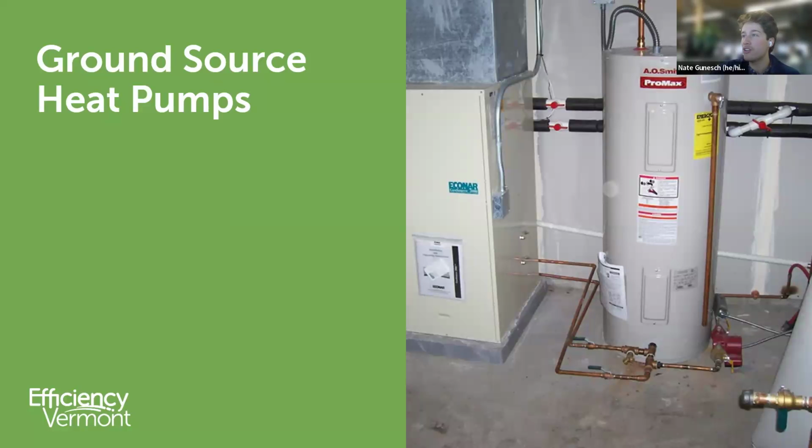A heat pump water heater, that seems less likely. The heat pump water heater, just to recap those real quick, they're pulling heat from the space that they're in, right? And they're so efficient that we don't lose a lot of energy by virtue of them doing that. But it would be difficult to use one of those to then preheat the water that's going into the boiler. I don't think that would necessarily be an efficient use of a heat pump water heater, but an air to water heat pump can be tied in.